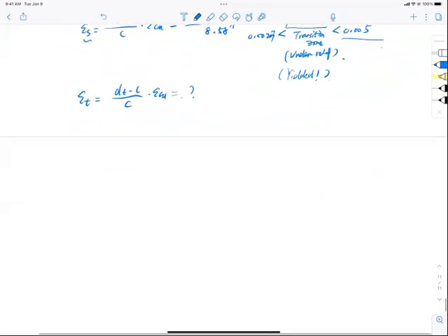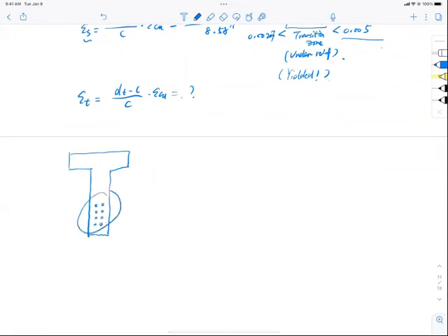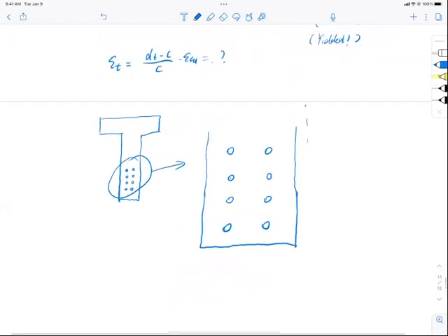It means that if I have my bars situated, say 8 bars, I'm just going to exaggerate. Let me put these 8 bars out first and zoom in. The height at the center of the group of bars is not exactly here, but somewhere in the middle, lower than that, and that is ds equal to 20 inches.